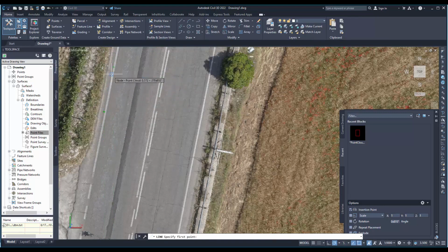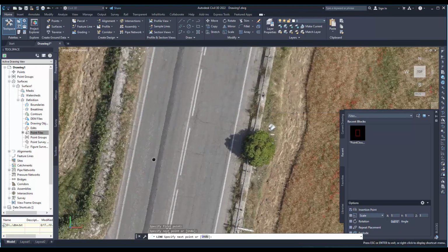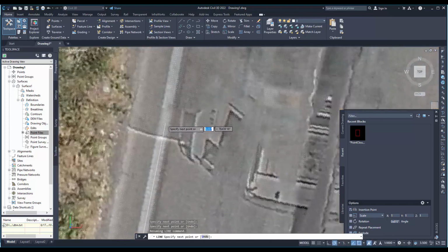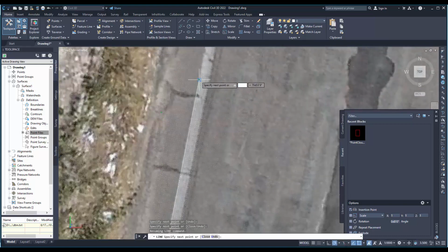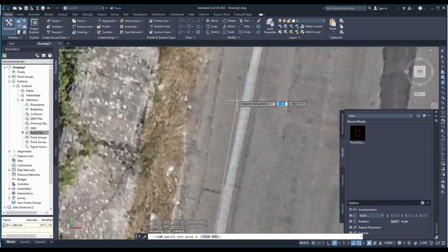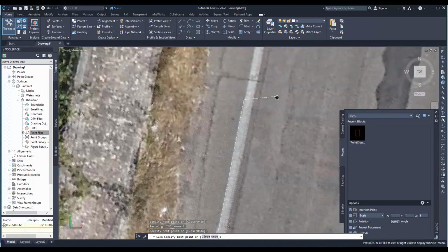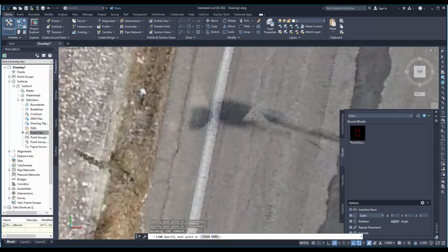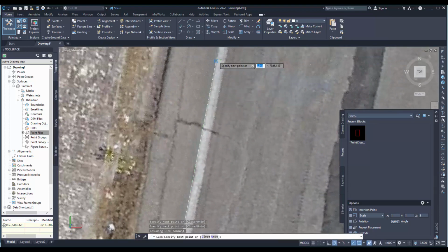So you see that the new point here will also have an altitude of 34.78 meters. Of course, for production we would zoom in more. Now we are able to see the points. So this is one way of how we could draw the survey map in 3D.